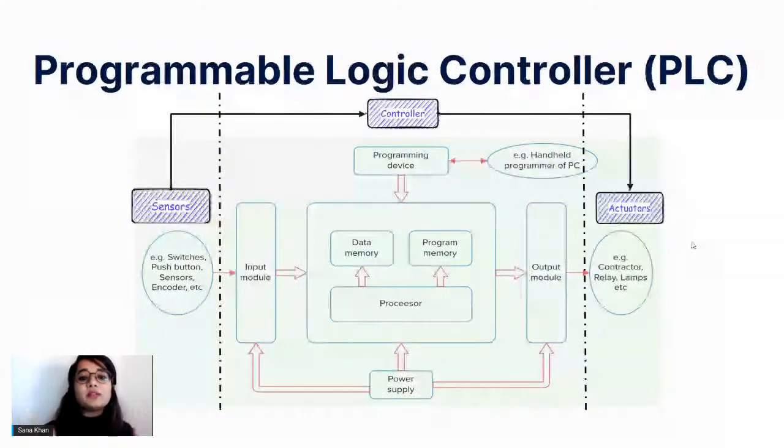So in between these dotted lines is something that I would talk to you about more, and what's basically happening over here. I have my sensors and my actuators, and they would be connected using wires to my PLC. So there needs to be some mechanism which connects to them. These are my input modules and the output modules. I will have the wires which connect to the input modules and the output modules. Now these modules are variable again. In the industry, they will have 4, 8, 12, 16 input modules and output modules.